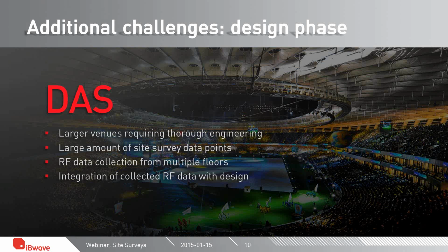So DAS systems, for instance, are typically required for larger venues that often require more thorough engineering. So large amounts of data will typically be needed, and there could be a lot more considerations to take into account in that case. So for example, in multi-floor towers, RF collection would need to be done at each floor, as they will not all have the same level of RF coverage.